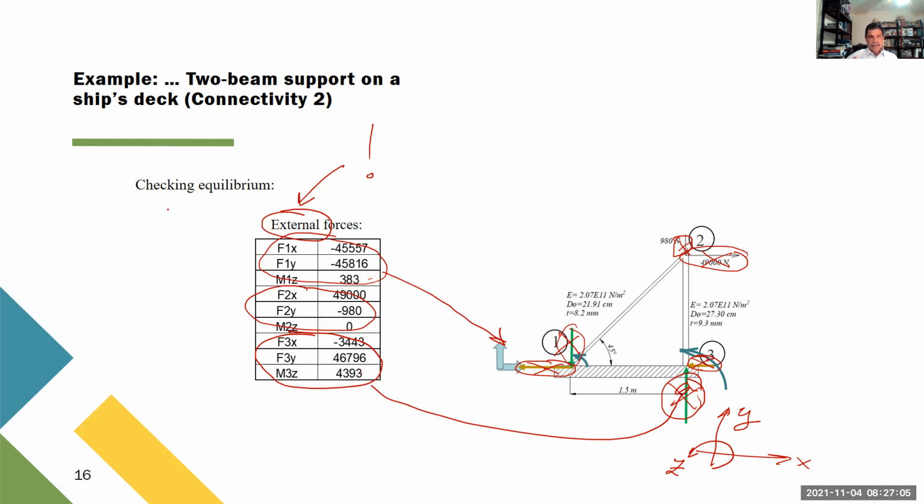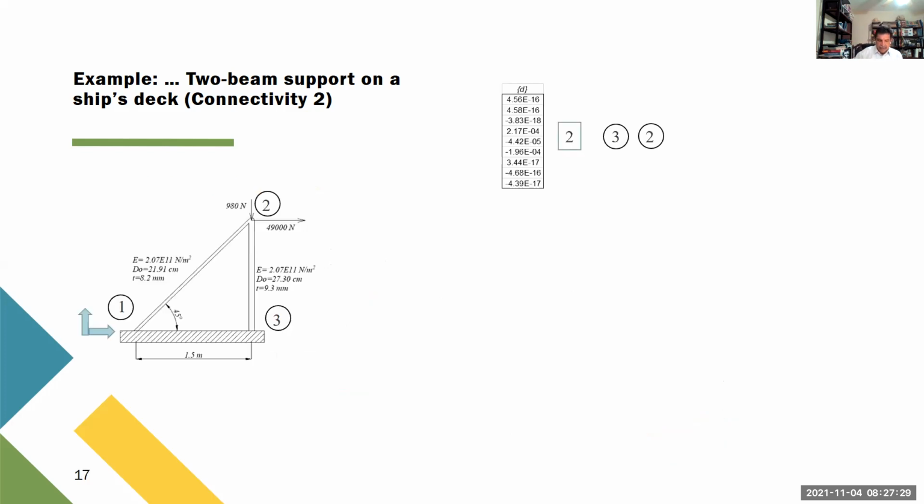Remember, internal forces, which is the next step, are related to cuts along the structure. When you do a cut, you have to consider P, V, and MZ. Those are internal forces: axial, shear, and bending moment. That's different, please. And we're using, remember, the convention that positive bending moment is a smiling face, and all of that. That's for the internal forces.